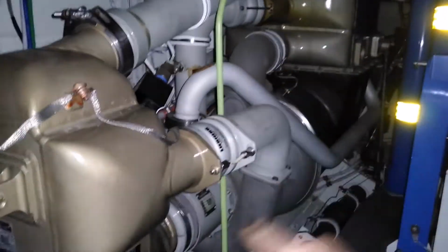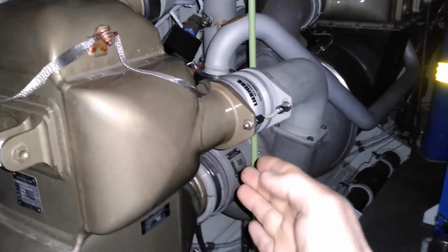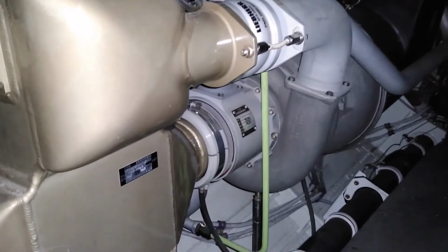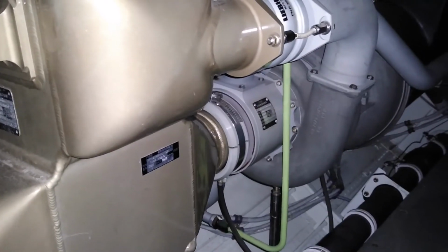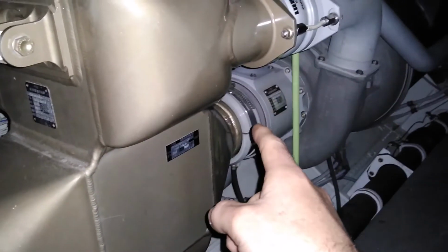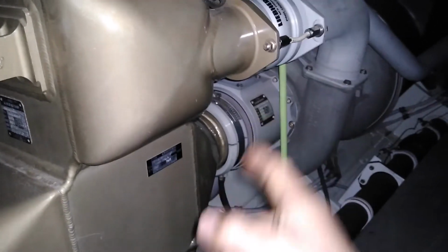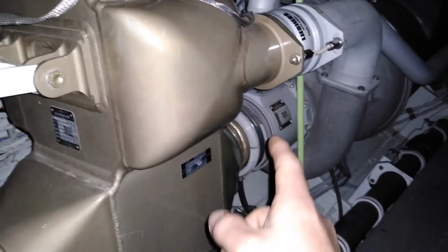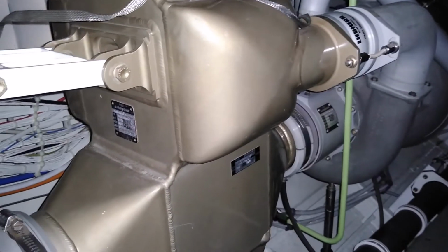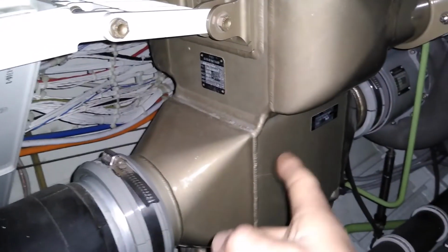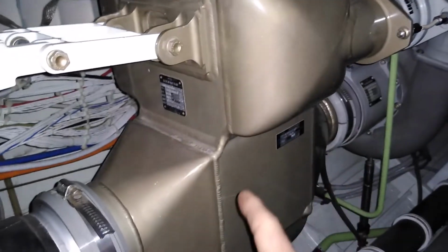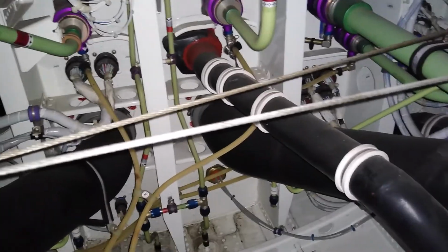So there's bleed air, high pressure coming in, powering all this, spinning the turbine. But here the air gets expanded. Its pressure drops, and so does its temperature. That's why here, at the outlet of the turbine, that's where you have the coolest temperatures. And it goes through here. Again, this is the same heat exchanger that extracted the water out of the air, and it gets pumped through there into the cabin.